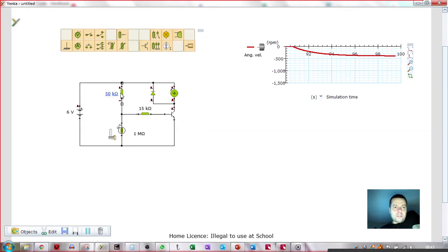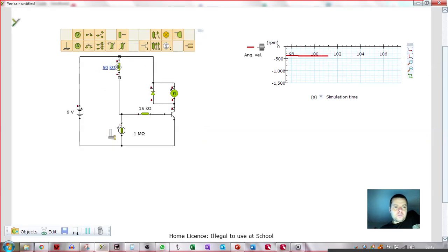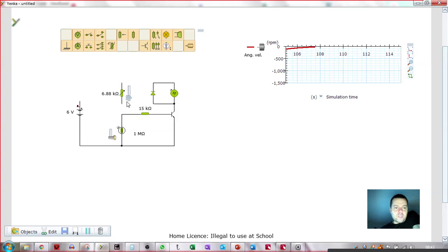So I can take that guy out. What is that? That was a fixed resistor. So I'll put it in there. And there's a component called a variable resistor. A variable resistor doesn't look anything like a normal resistor. It's like a plastic block with a wee screw head on it.